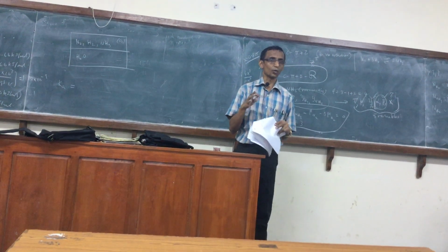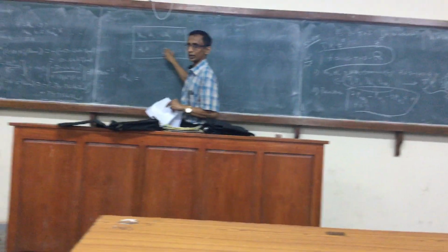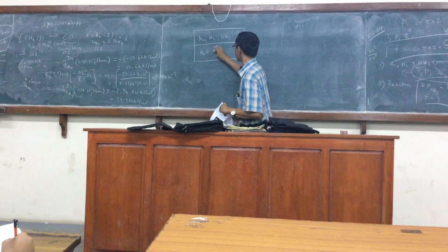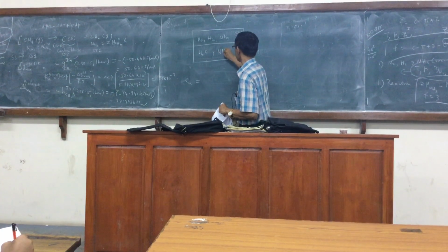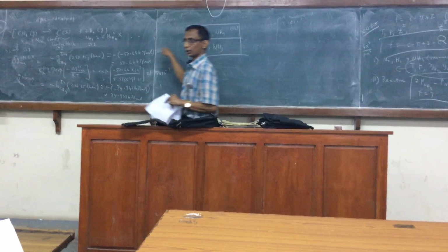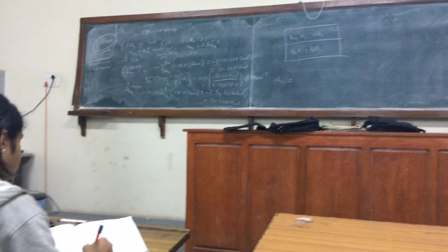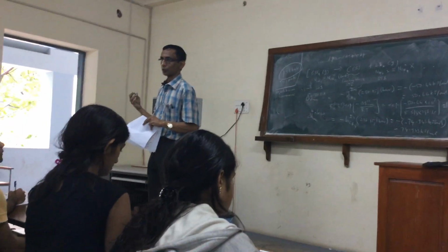The values are very low. So it's a good approximation to neglect the absorption of nitrogen and hydrogen in the water. And then I have only NH3, and here he says neglect the reaction of ammonia absorbing in water, which actually gives a reactive absorption also, in the sense that you can form ammonium hydroxide.